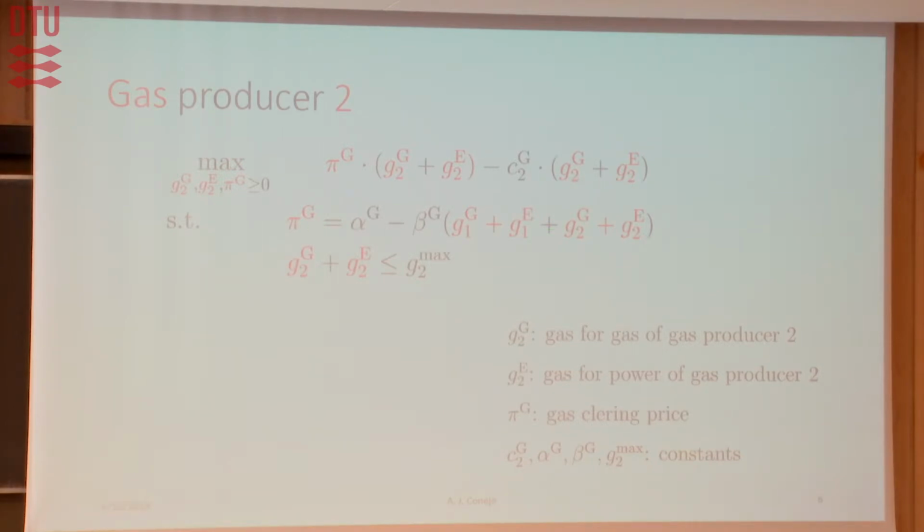In the same way that you're solving an OPF problem, the production, the P and the Q of every generator are control variables that control every generator, but the flows in the lines are variables of the problem. And you have to define them like optimization variables, even though you don't have control over the flows. So it's the same thing. Perhaps a little bit more confusing here, but for solving this problem, this is a variable you have to take the derivative with respect to as well. Otherwise, you don't get the solution.